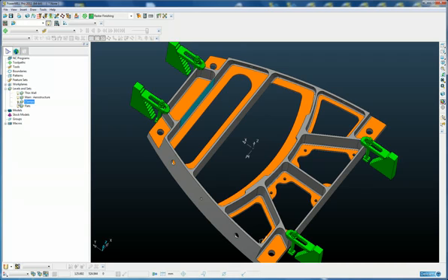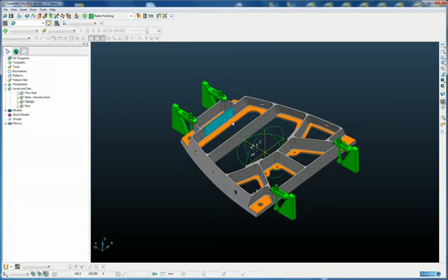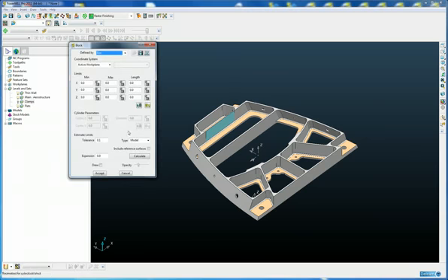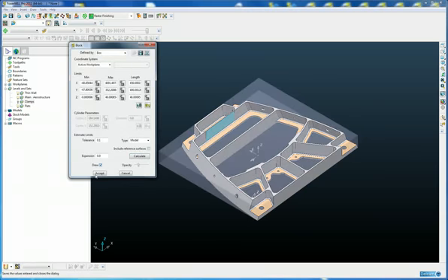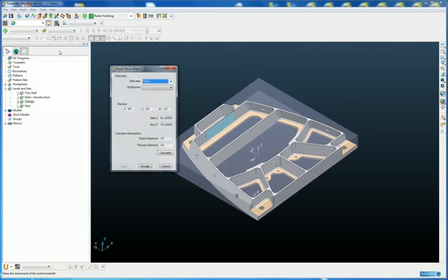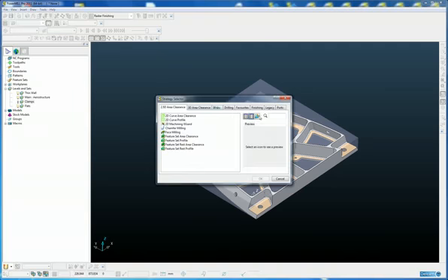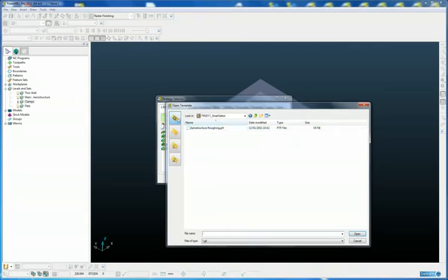So we have our level called clamps again. Let's switch off the clamps for a second, and we're just going to set up our block. So we're going to calculate the block, accept. Just going to reset my safe working height, safe Z heights. And now I'm going to load in the template I saved earlier.